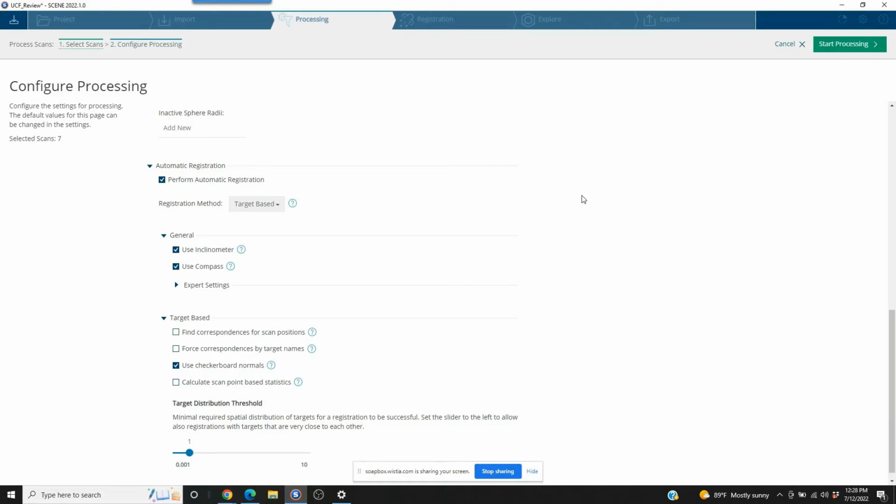The computer's looking at those three targets, spheres that didn't move. So 1 to 2, 2 to 3, 3 to 4, there will always be at least 3 scanned targets that don't move between 1 and 2, between 2 and 3, and 3 and 4. Obviously, they're going to be different from 3 to 4 than it was from 1 to 2, but it's only worried about putting together 1 to 2, 2 to 3, 3 to 4, 4 to 5.